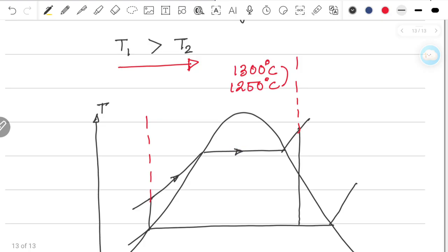That is happening because of what? Because of the flue gases. So flue gases are basically transferring their energy to the water for phase conversion and superheating. So flue gases, let's say, enter at A and exit at B. Here, if you look, there is a huge temperature difference at each and every point. So this temperature difference will cause the external irreversibility on the boiler side.